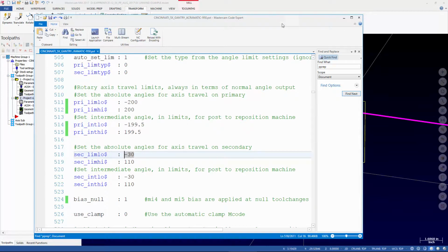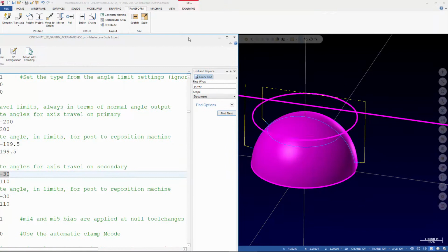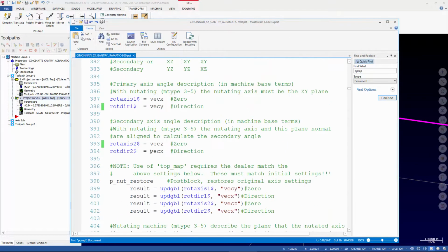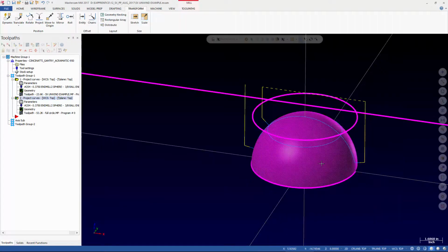If we had kept that same start point, we could have tried reversing the direction, and that may have let us get in there. But the question is, what works on the real machine? On the real machine, if this side really is B45 positive, then we can't hit negative over here. It just won't reach. So that means we have to approach it from this side, and all of our start points for our paths should be on that side as well.